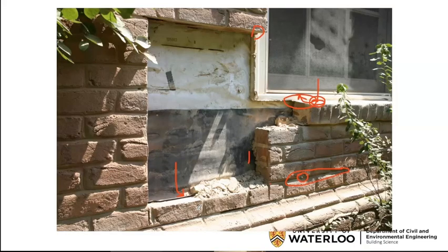The reason they install nylon rope, and I don't know how common this is, but in parts of the States it'll still be common. It used to be that they would use cotton rope. And the advantage of the cotton rope was that it wicked water. So water that got to it would wick to the front and evaporate. But better than that, it took only a few years and then the cotton would rot. And then you'd have an open vent hole and a weep hole.